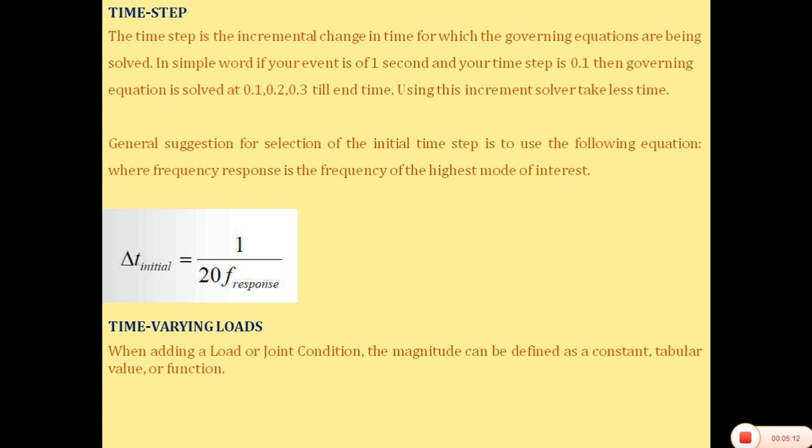When the load or a joint condition, the magnitude can be defined as a constant, a tabular value, or a function. It means that when we are adding the load, we will give the load with respect to time. We will do some tabular work and give the time as per the time step. So this is very important. Now we'll move to the problem.